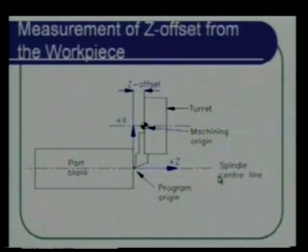The way the offsets are going to be measured is, you normally put a part blank of known diameter and length and set the job inside the chuck, and set the first tool to come into operation and bring it and touch it to the surface, so that when it is touching this surface, you make it the z-axis 0, and similarly when you bring this and touch it at this point, you will be setting the x-axis.